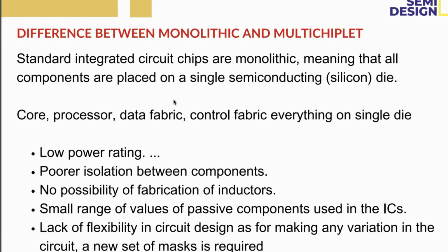Okay, monolithic is nothing but all the circuits integrated on a single chip or a single die. So from that, AMD introduced the chiplet design. Chiplet in the sense both cores and IO devices will be separate. There will be a number of dies. A chip is divided into a number of dies, and each die has some CCX configuration and IOD configuration. Okay, we will discuss all those things in today's session.